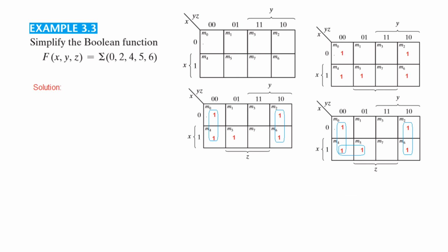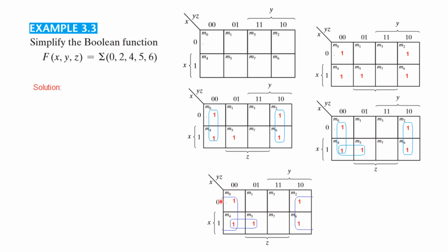We could do like this, 1 and 2 and 3, but our effort should be to find, if possible, to get 4 or 8. So if you look here, we can make a 4 pair, this and this. So let's see. So this makes a 4 pair, so we'll prefer that. And then this can be paired with M4, so this will also be a pair. So this is the best option.